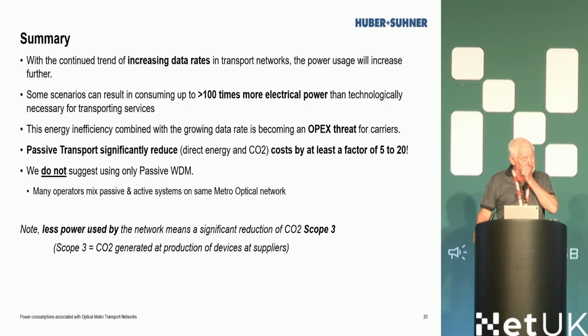We're seeing requests for 250 gigahertz passband on WDM because of the 800 gig and beyond transceivers with the associated modulation techniques. So just make sure that if you're using passive WDM, any passive WDM you buy now, make sure it's got greater than 75 gigahertz passband.